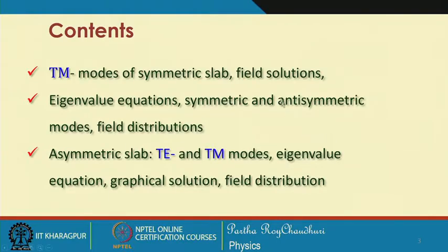So, we will continue with the TM modes of the symmetric slab waveguide, and we will look at the field solutions, which we will see are almost similar to those of the TE modes. In this context we will work out the eigenvalue equation for the symmetric and antisymmetric modes, which will be almost similar. Then the field distribution.